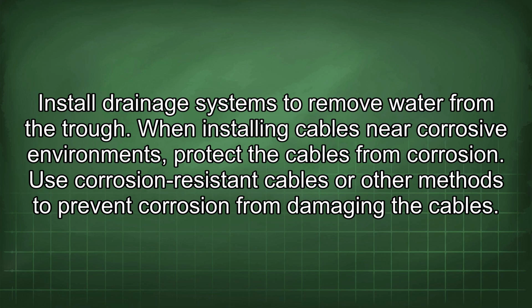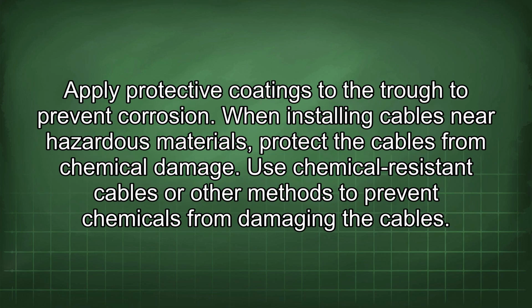When installing cables near corrosive environments, protect the cables from corrosion. Use corrosion-resistant cables or other methods to prevent corrosion from damaging the cables. Apply protective coatings to the trough to prevent corrosion.